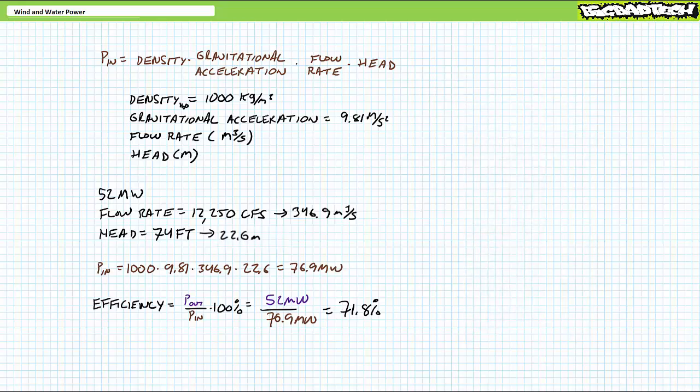As with wind turbines, the input power to a hydropower turbine is dependent upon these input properties. Turbines with more differential between the top of the reservoir and the outlet, i.e. higher head, and those turbines with larger draft tubes can accommodate higher flow rates and thus experience more input power.